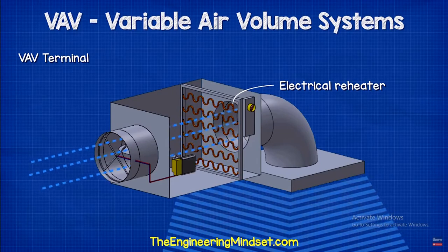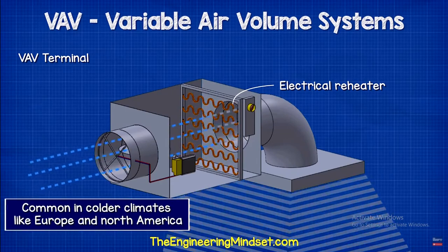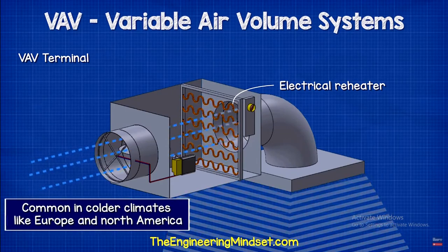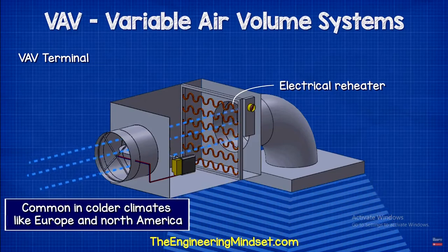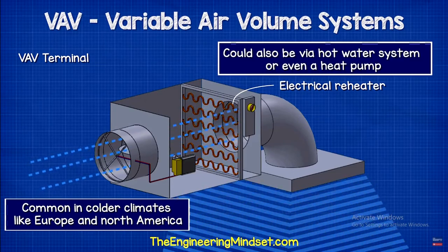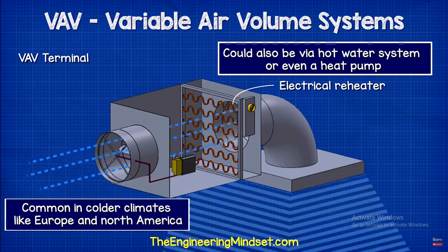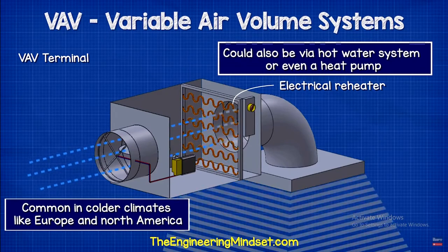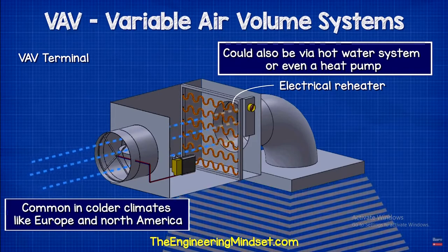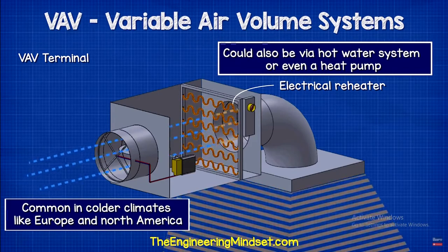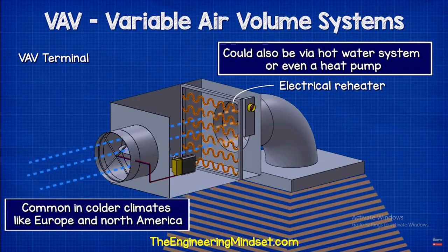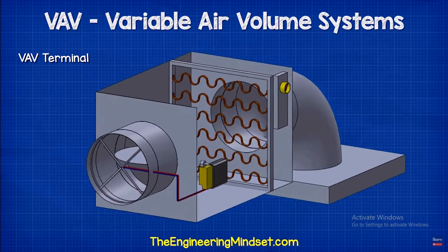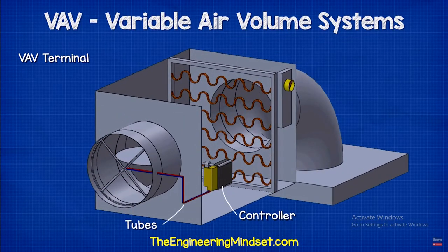By measuring the pressure at different points across the cross-sectional area, we can therefore calculate the average air velocity or the average flow rate into the VAV box. So how is this done? If you notice on the metal tubes, we have some holes. There are some on the front as well as the back of the tubes. Now, if you imagine the air is entering and colliding with the tube, and then it flows around it.